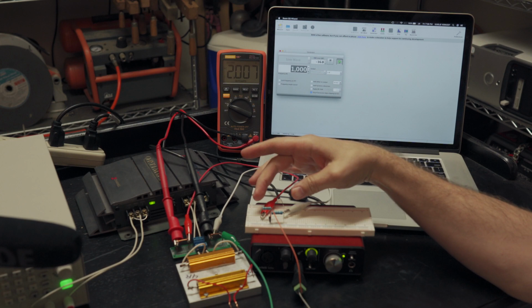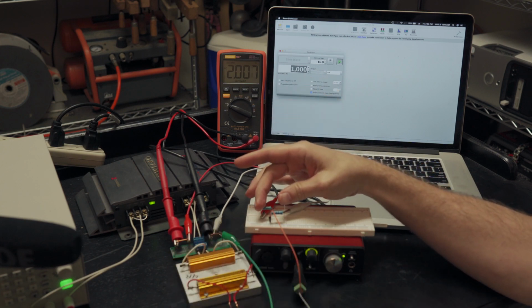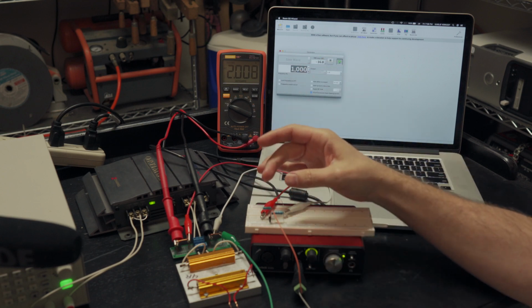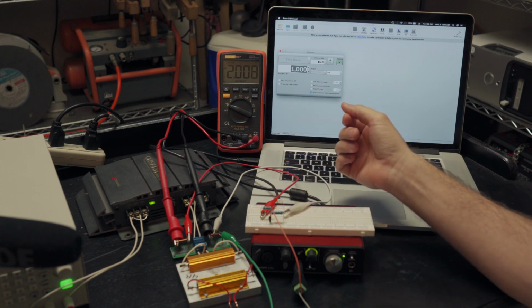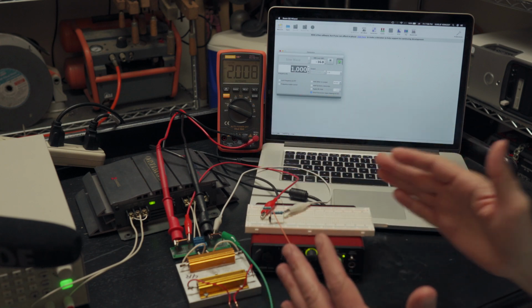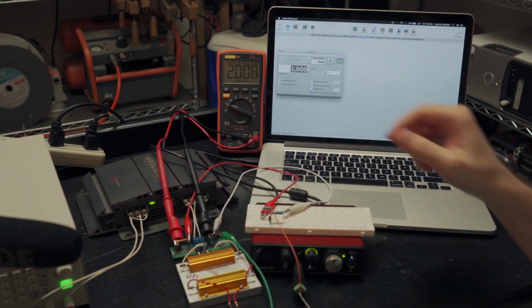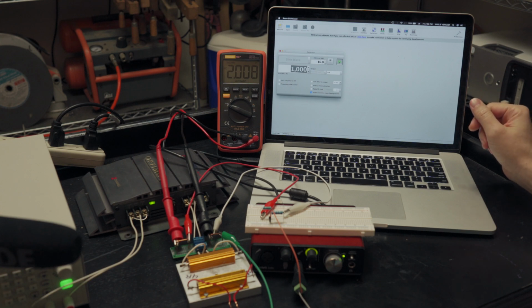And so I've got the amplifier hooked up across the 10K and the 1K, as well as the load, of course. But then I have the measurement device connected between the 1K and the ground. So that means it's like an 11 to 1 or whatever ratio that it's being taken down at. That will allow us to run the amplifier up to its maximum power while not overloading the voltage input of the device. And your device's voltage input may vary in what it's asking for, right?